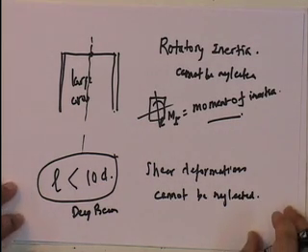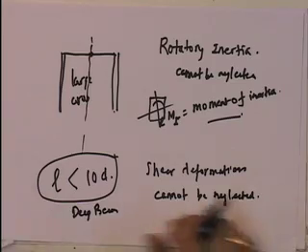Typically, in this particular case we only looked at the flexural deformations; the flexural motion of a simple beam only had flexural deformations and a linear inertia term. Now, if you have a deep beam, you not only have to consider the shear deformations, but you also have to consider rotatory inertia.